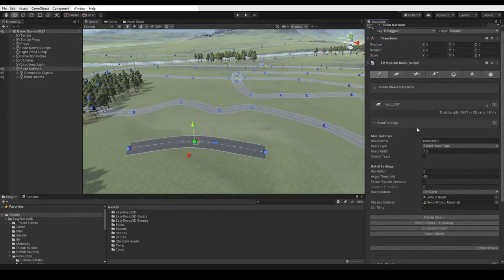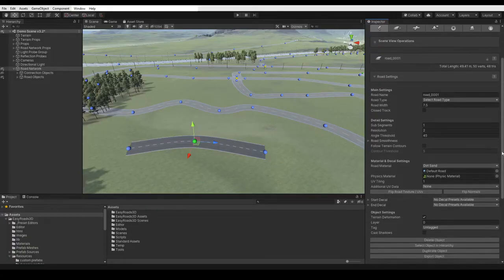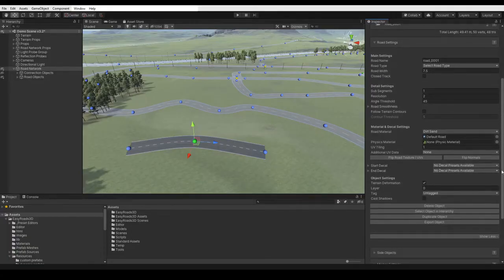We have a range of options here in the main road section. At the bottom, we can expand the options with additional settings. This option can be used to tidy up the inspector when it turns out that you will generally not use these additional options. We can see here that indeed no road type is selected for this new road. The displayed road properties depend on road type selection. In this case, the road width and material options are visible and editable because no road type is assigned.